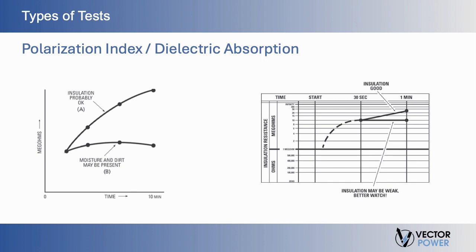The net result is that with good insulation, leakage current is relatively small, and resistance rises dramatically as charging goes to completion. This changing resistance is precisely what an experienced technician wants to see. Deteriorated insulation will pass relatively large amounts of leakage current at a constant rate for the applied voltage. This will flood out the charging effect.